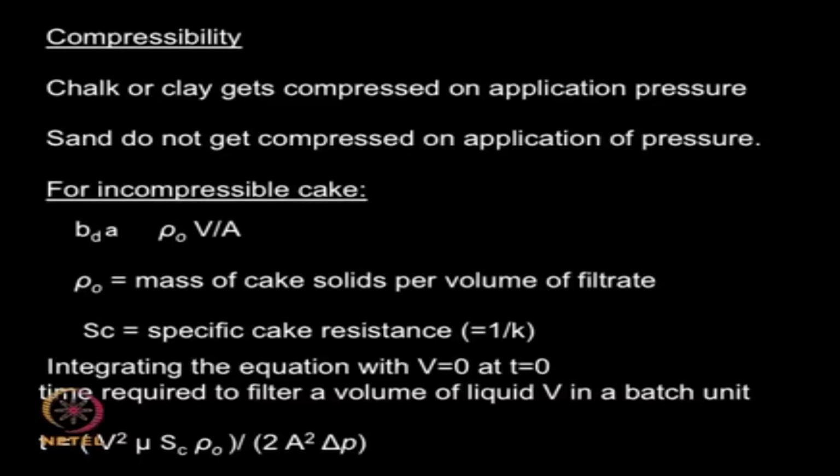So for incompressible solids the rate of filtration can be increased by increasing pressure, whereas if it is a compressible solid like clay or chalk, by increasing the pressure you are in trouble, you will be reducing the flow because the material gets compacted.